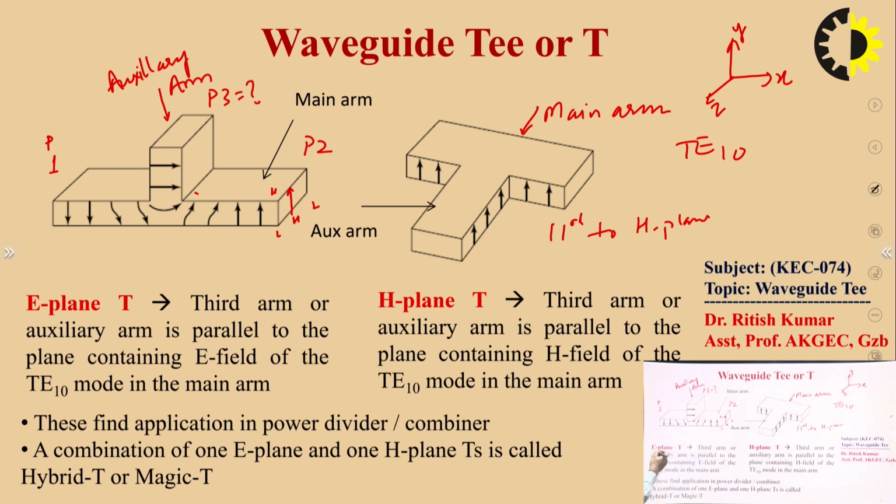If we apply inputs in opposite phase at port 1 and port 2, then we have the addition of the power at port number 1 and port number 2 appearing at port number 3. Suppose P3 should be equal to P1 plus P2 in the condition of phase opposition.